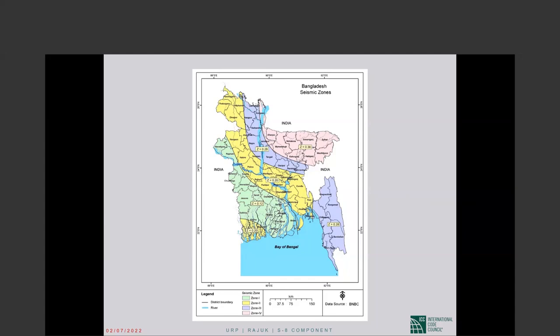So depending upon the earthquake, it may become more critical for the building or may become less critical. You see what I'm saying? Depending upon the predominant period of the earthquake, the lengthening of the period of the building may put it in the critical range or may take it out of the critical range. So what would happen, you do not know.